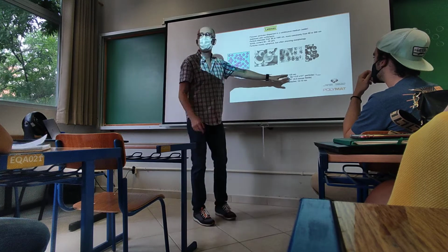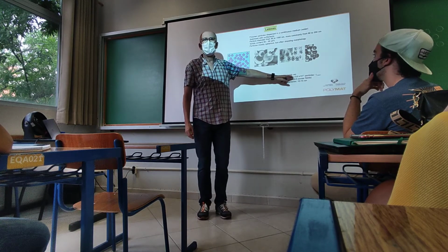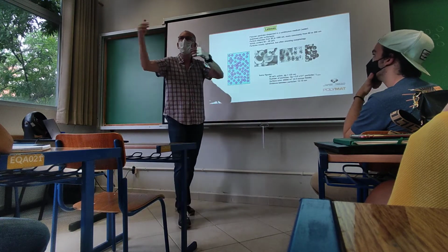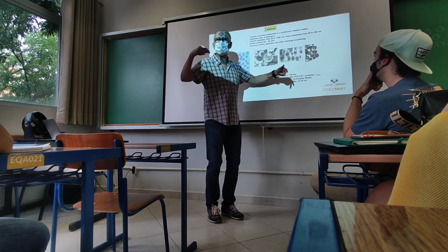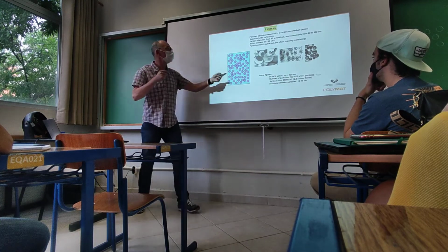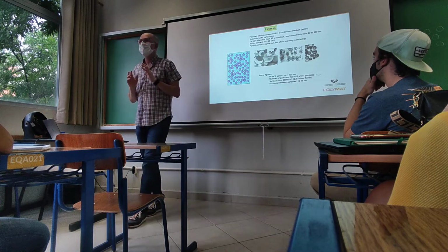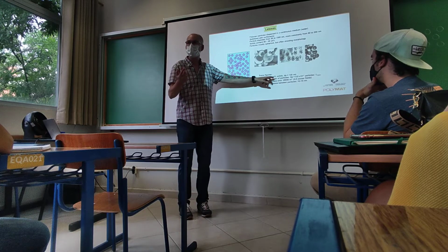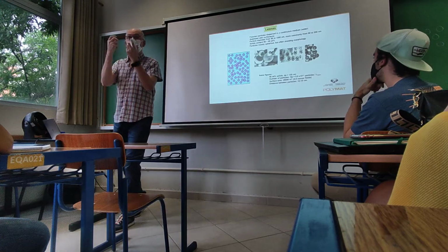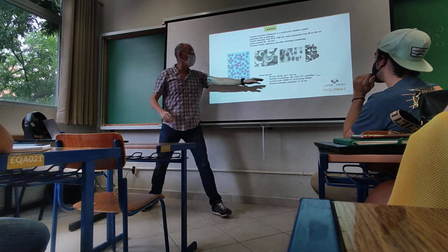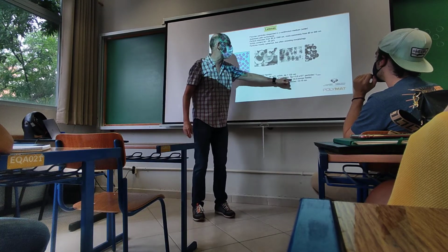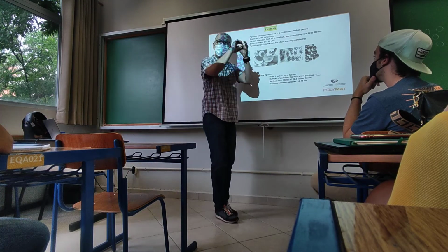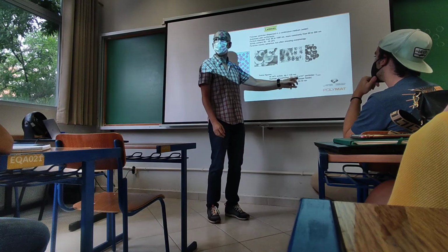Okay? But you can do this calculation. I will give you some time. Tomorrow you will let me know if you are able to do this calculation. Otherwise I will show you how to do the calculation. Okay? So try to do the calculation assuming that the particles are spherical. With this information, the particle size and the solids content, and knowing the volume of a particle, assuming that it's spherical, you can calculate the number of particles, and of course you can also calculate the surface area of the particles in 1 liter of this latex.